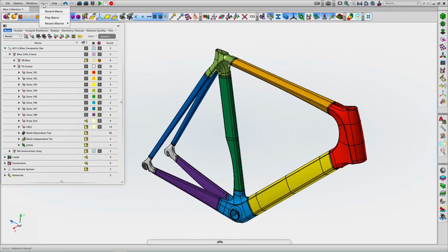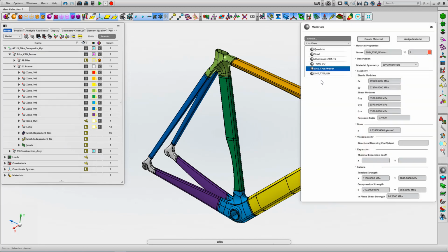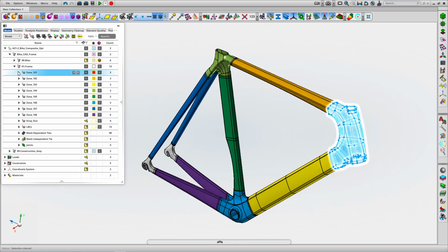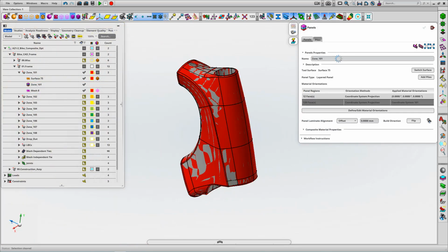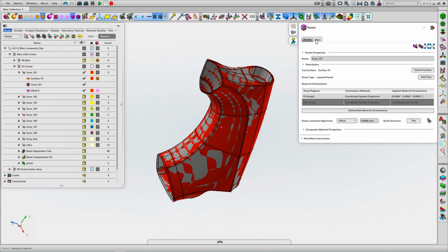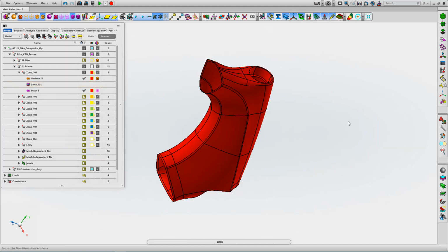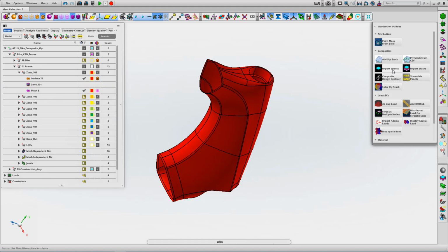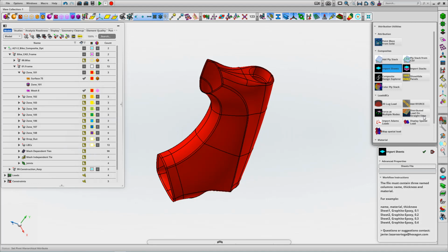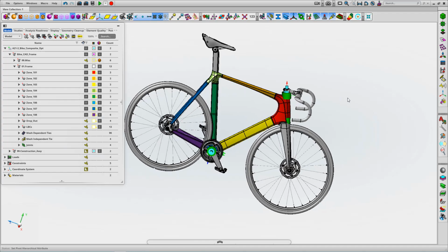Okay, many different ways of creating this stuff. So we've shown the manual approach, but we can use the embedded Python API within the Apex environment to read in discrete materials and stacking sequences from external sources. So we can read in Excel data discretely to build up our zone definitions. Okay, so just showing quickly here. So we can bring in the sheets, which are the ply materials, so material and thickness, and then our stacks, which are our stacking sequences.